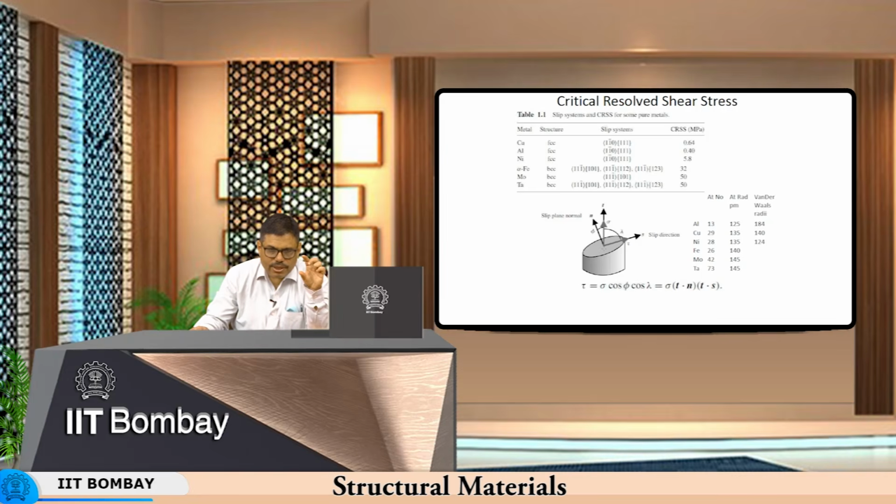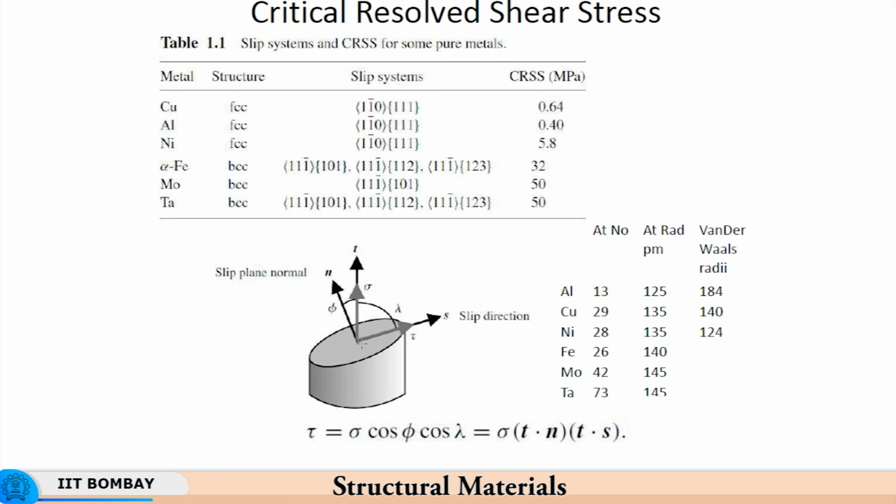There are two things. One is the tensile load and this area. Now the component of the tensile loading in the normal direction to this plane will be given by T cos phi. It will be given by T cos phi divided by this cross sectional area, which will give us the stress, because load divided by cross sectional area is the stress.